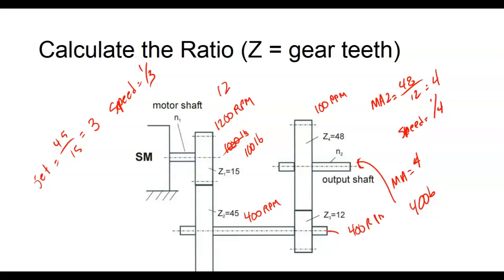That means, for torque, it would be foot-pounds. So that's why we measure torque that way. If I put 100 foot-pounds over here, I get 400 over there. Speed was real easy to work with because we know it's a speed divider. But if speed goes down by 1/4, then torque's got to be going up by what?